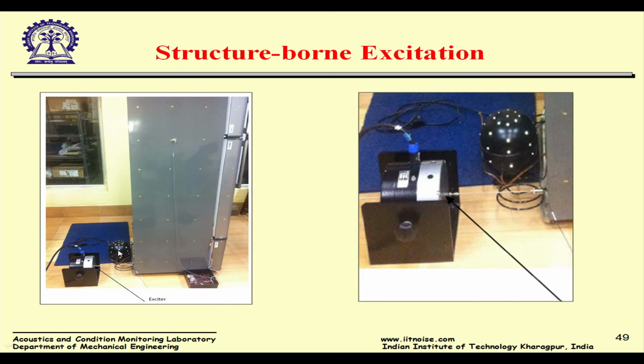So you can see here in this figure, the compressor is removed. We could not totally remove it because of the tubings, but you could displace it. And then I gave in a structural input wherein we could know the forces going into the shell of the refrigerator and measure the response in the interior of the refrigerator. And if you see here, these white shiny marks are the marks for the laser vibrometer.